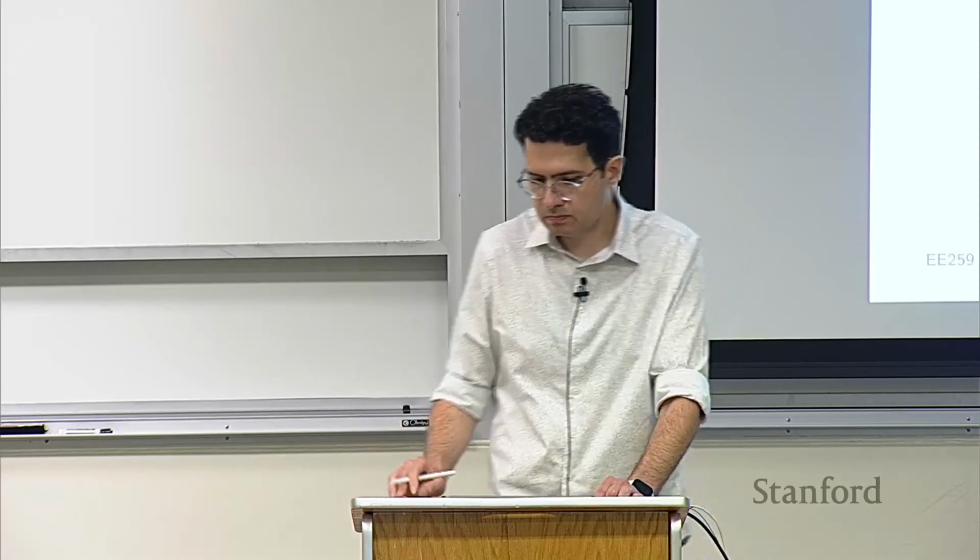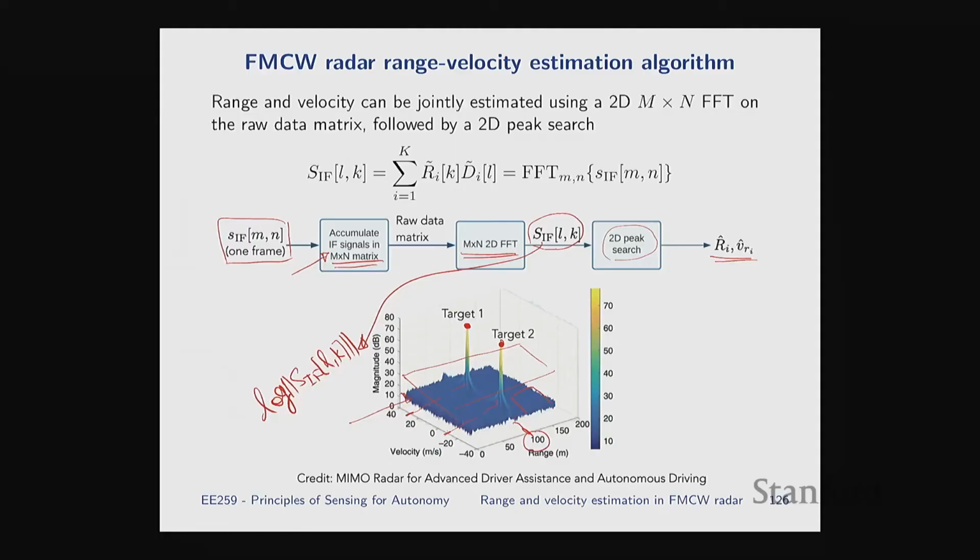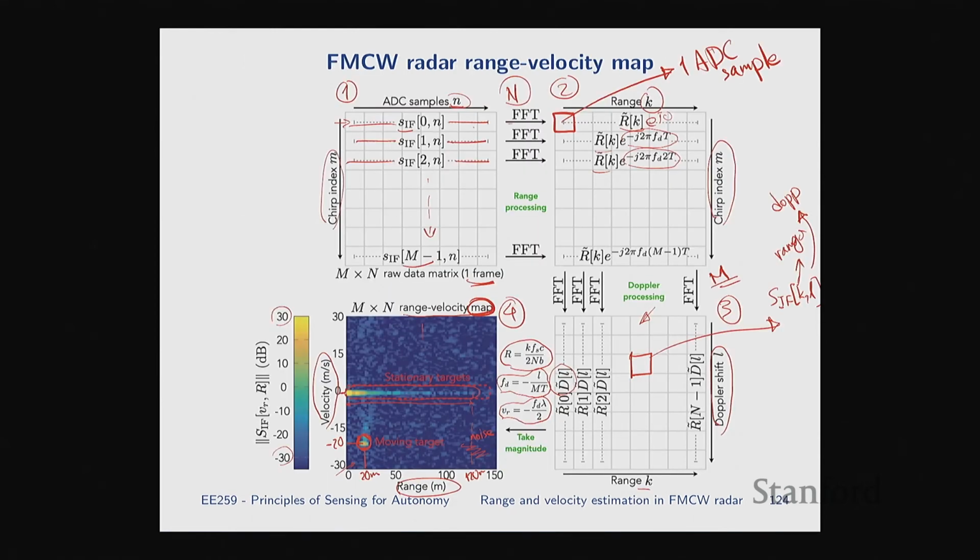Yes, so if you want to estimate SNR, one way of doing it is to look at part of this where you know there's no targets and average that. That can give you your noise level, the noise floor. Then you take your target value and divide it by the noise floor, and that gives you a measure of SNR. Or maybe the previous one is better. If I go over here, where you know there was no target, you can just average here, and that gives you your noise level. Then use that to estimate SNR. That's one way of doing it.